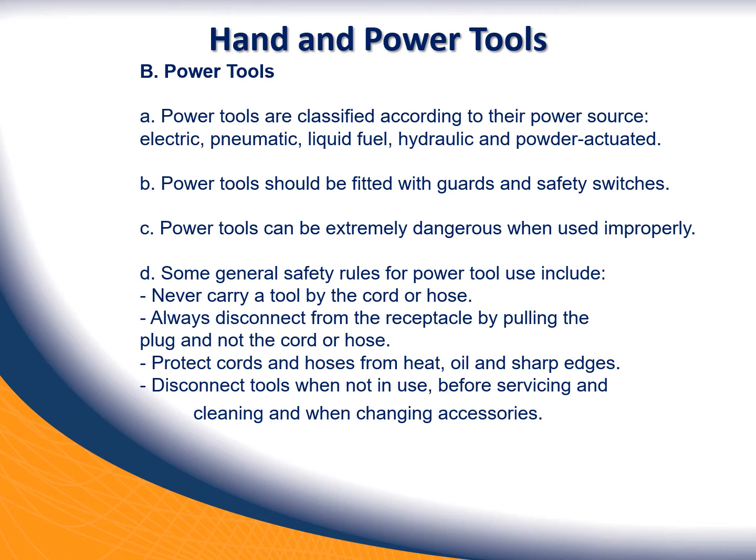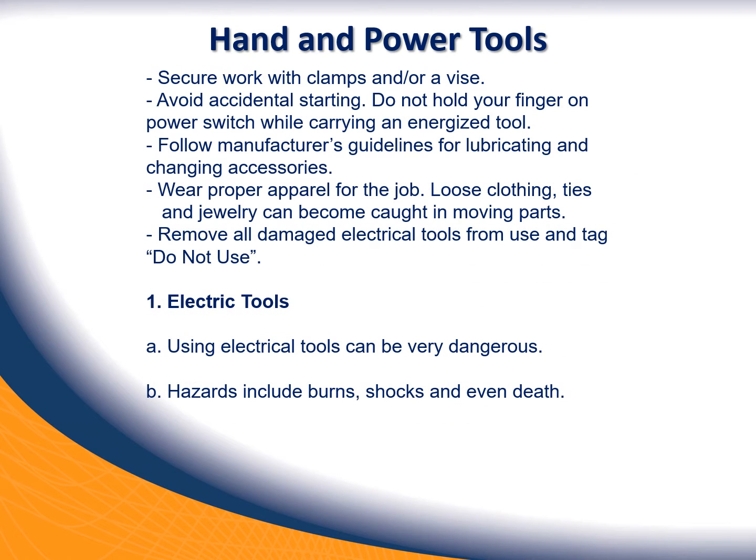If you don't know how to use it, either find the manual for it or ask somebody how to use it properly. Some of the general rules are: don't carry the tool by the cord or the hose. Disconnect it when you're not using it. Make sure the cords and the hoses don't get cut on a sharp edge or heated up and melted. If you're using a smaller piece of material, you can use a clamp or a vise to secure the work that you're working on.